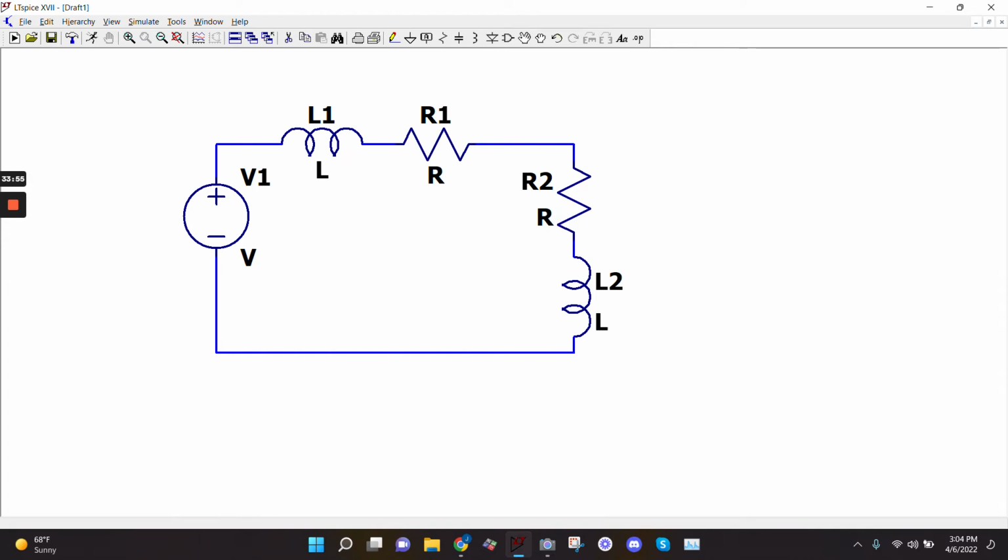So basically, you have two coils. Like, take my two hands as the two coils. If you put an AC voltage on this one, it will induce a voltage on the other coil because of the magnetic fields that are literally being induced by the current flowing. But if you just put a DC current through the coil, it's just going to act like a wire and it won't induce any voltage on the other coil.